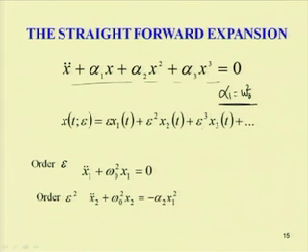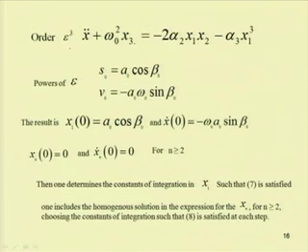By substituting this in the differential equation and ordering by the order of epsilon, epsilon square and epsilon cube, one gets a set of equations. Substituting the solution of the first equation, that is x 1 double dot plus omega square x 1, into the second equation, and similarly the solution of the second into the third, one can find the required response of the system.